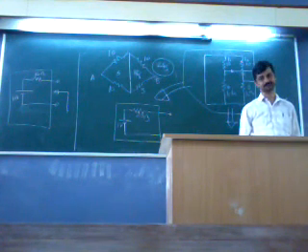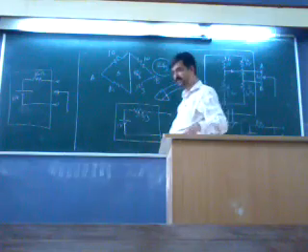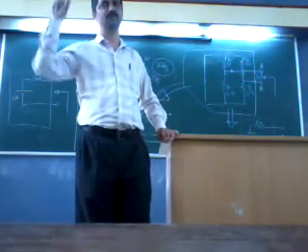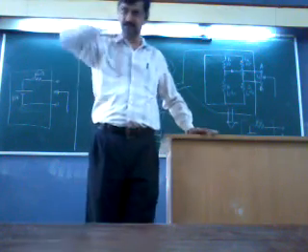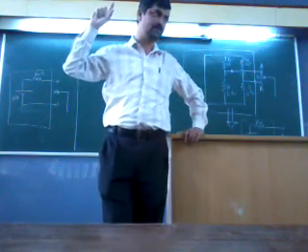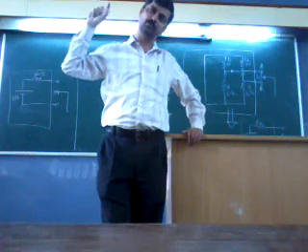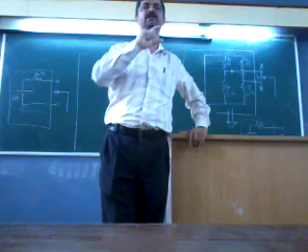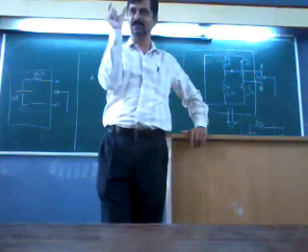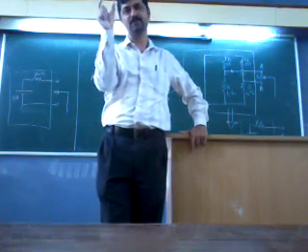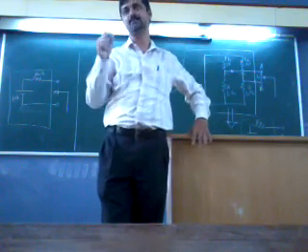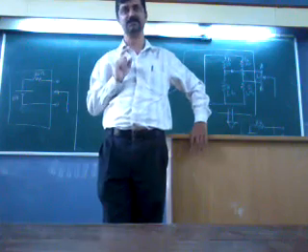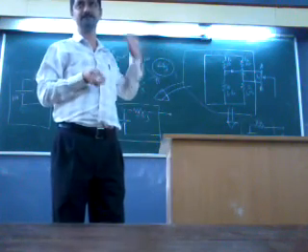Right? So Thevenin's equivalence looks like one voltage source and one resistor for any circuit consisting of resistors and voltage sources. The voltage of the Thevenin's equivalent model you find by open circuit voltage between these 2 points, and the equivalent resistance RTH is to be found by shorting the voltage sources. Is it correct?